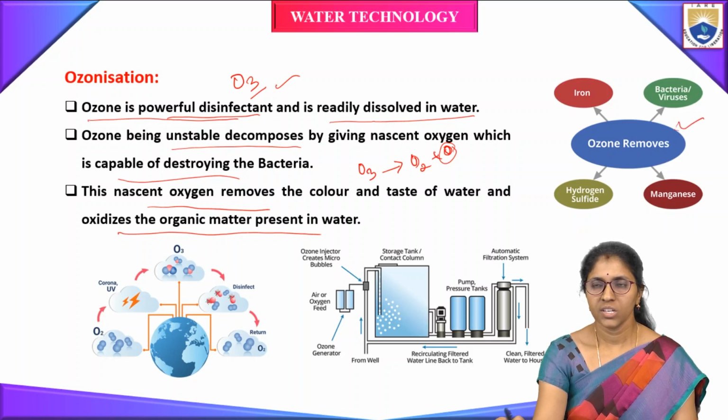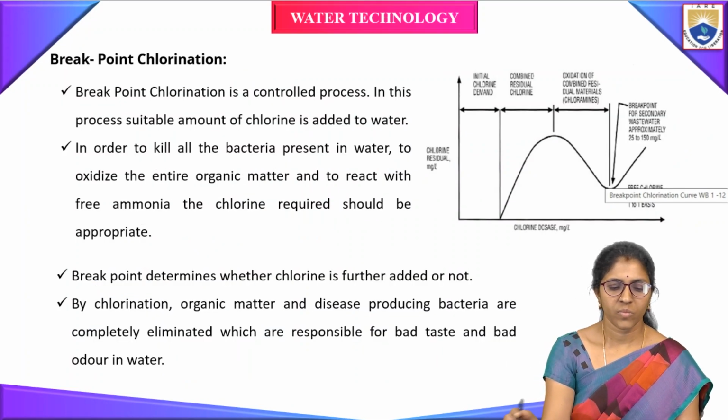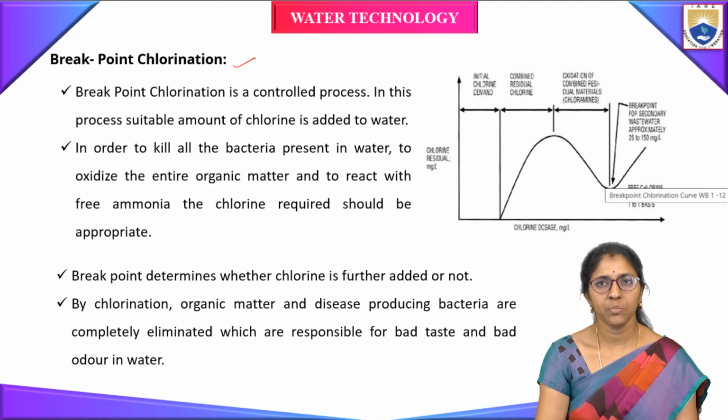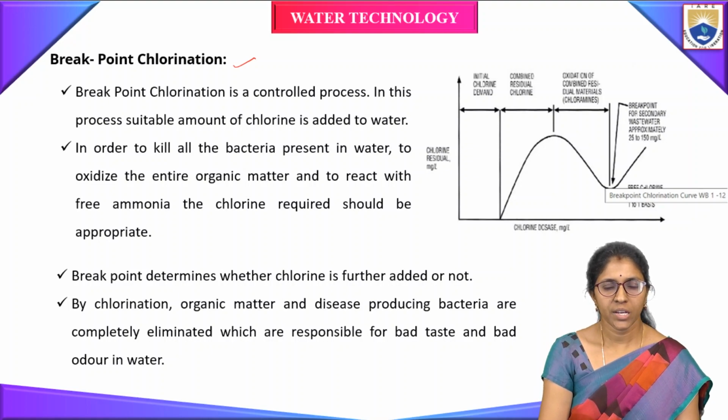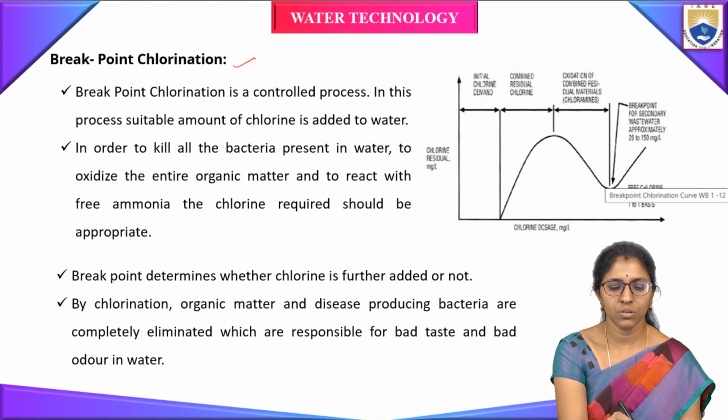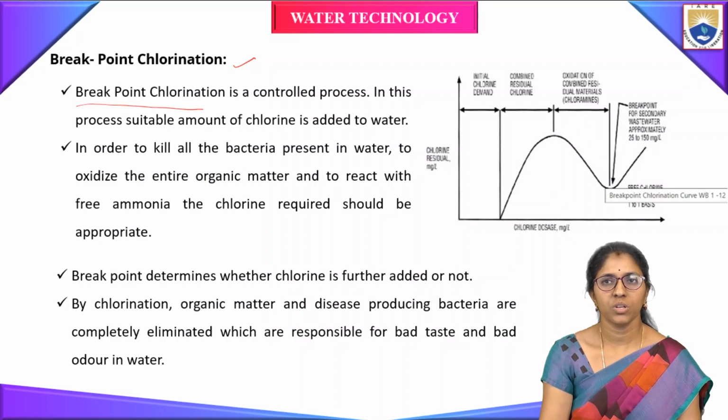This ozone removes iron, bacteria and viruses, hydrogen sulfide from the water, and also manganese from the water. So this is ozonization. The last technique is breakpoint chlorination. Breakpoint chlorination is a controlled process.